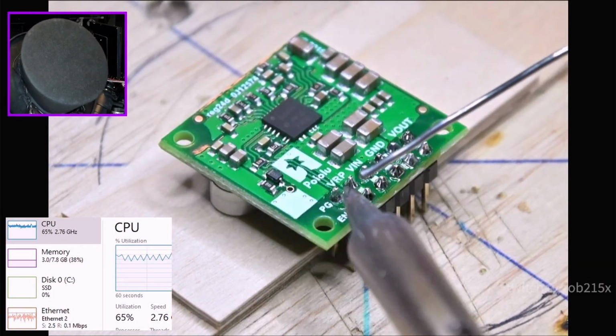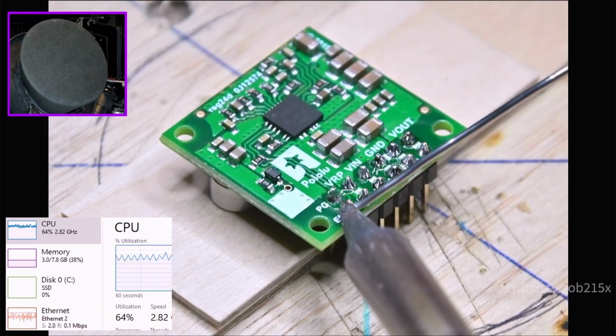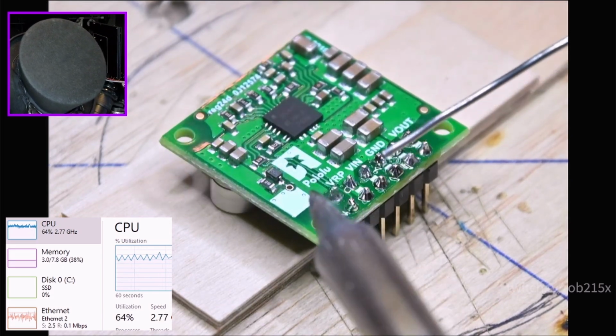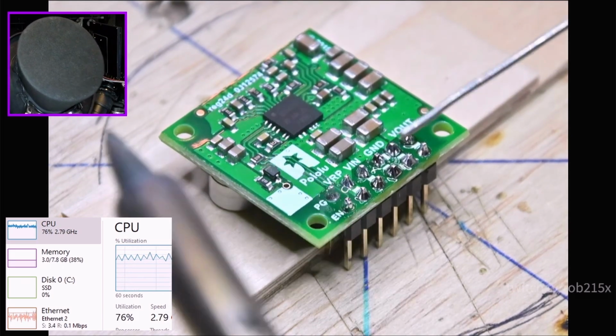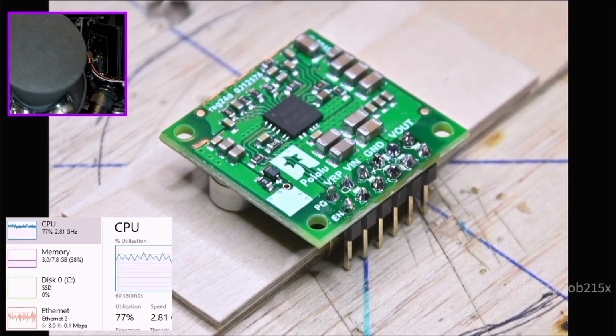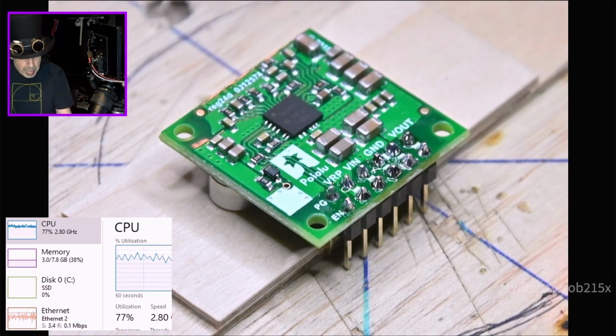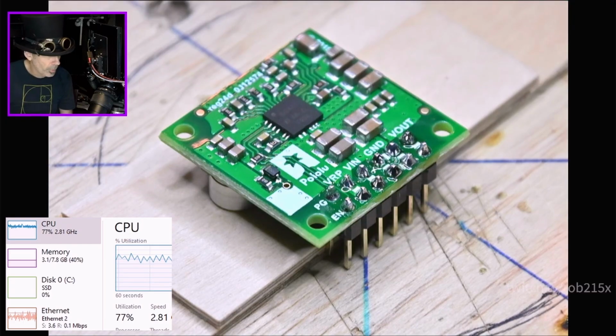This isn't really a lesson on how to solder, but it's a skill that you should learn if you're going to be building anything electronic. You really need to get to the point where you're comfortable that your solder joint is good without leaving the soldering iron on any joint for a long period of time, because you don't want to transfer all the heat into the electronics.